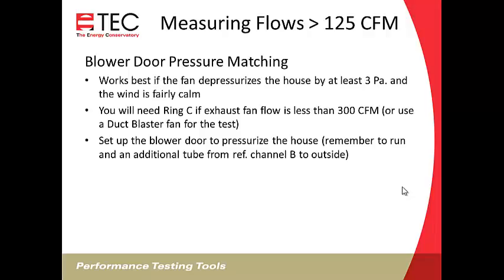So either you have to run around, go out another door and cap the fan, or if we do have fan caps that are like shower caps that fit over the blower door fan, or you could use just a piece of cardboard or something on that order to cover the fan to get a baseline reading. It's very important to get a baseline reading to get a sense of how windy it is, and it's important to zero out that pressure to start with, so to get an accurate reading.